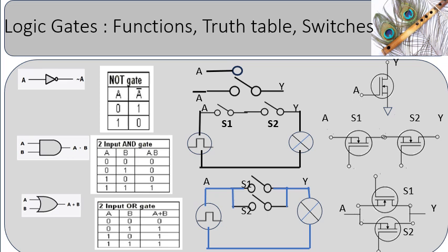Voltage-operated MOSFETs are used as logic switches and realize logical functionality. N and P MOSFETs connected in different configurations implement different logical functions. An N or P MOSFET operating in common source configuration acts as a simple inverter. Series MOS switches implement the logical AND operation.